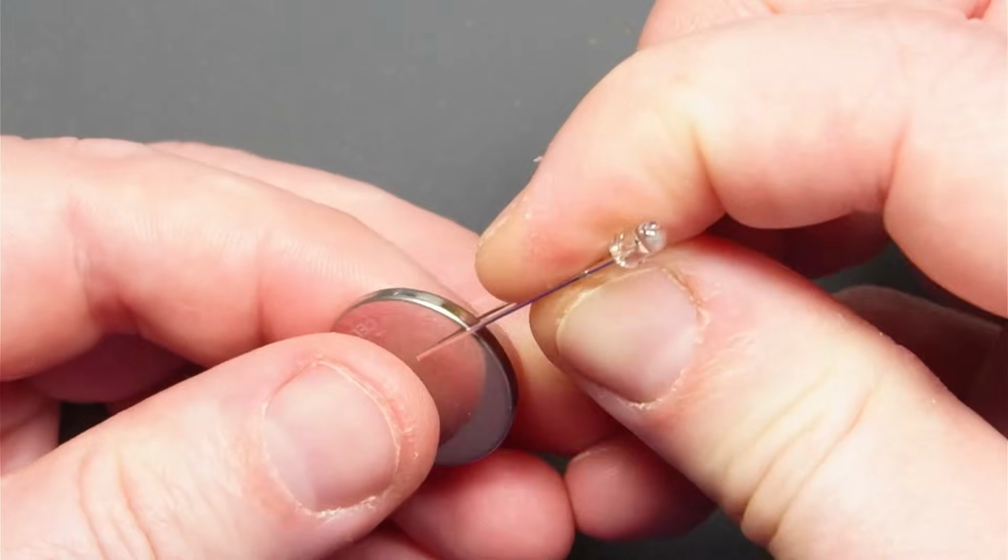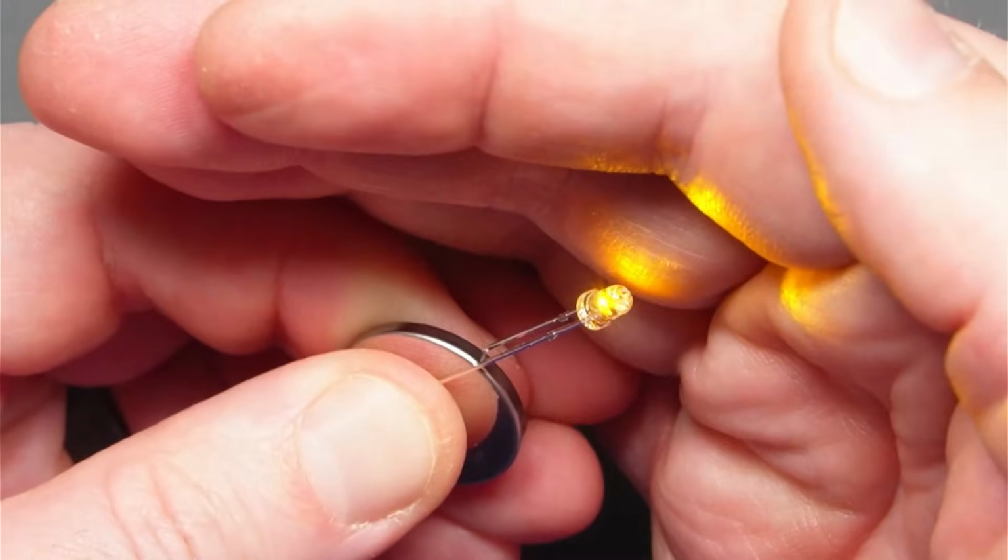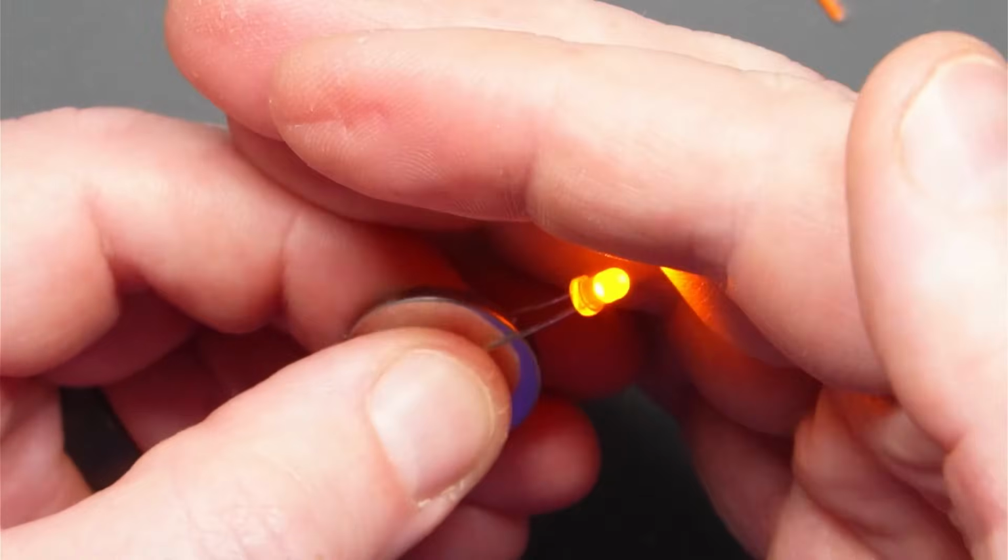Now, typically when you have flickering LEDs like the ones you can buy from Terrain-Tronics, they're very easy to use, but if you switch all of them on at the same time on a build, then what tends to happen is that they all start off synchronous. So the whole scene is flickering up and down in sync with each other. And it's only over time that the little differences in the clocks and the timing inside the chip inside the LED cause drift, so that they start looking random from each other. Ideally what you want is 8 real LEDs acting completely randomly.